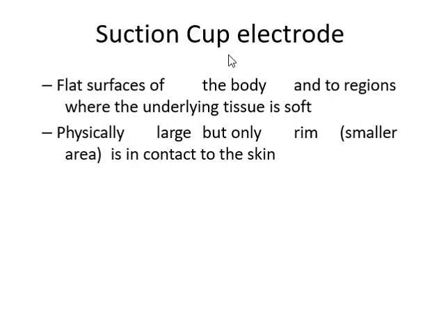And the next one is the suction cup electrode. A suction cup electrode is for establishing electrical contact between living tissues and an electrical conductor. The electrode comprises a cup-shaped membrane that terminates in an opening defined by a peripheral lip having a minimal radius of about 0.015 inches.